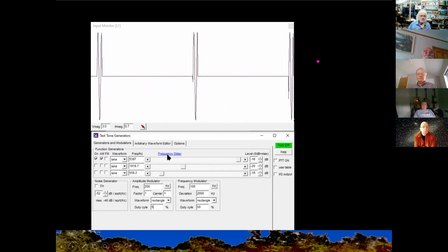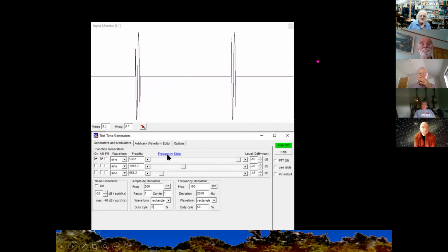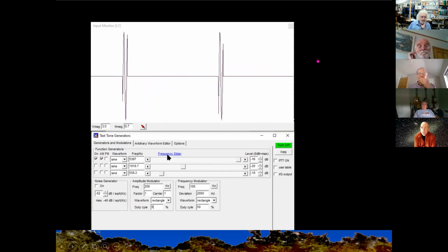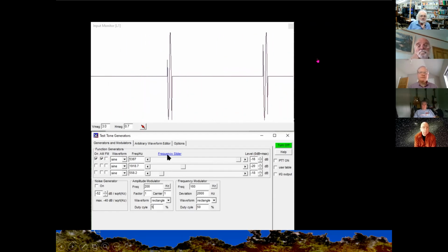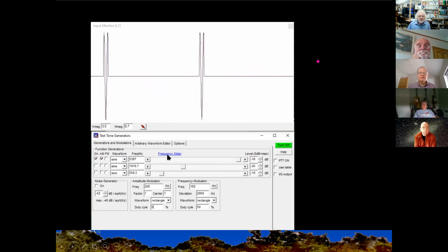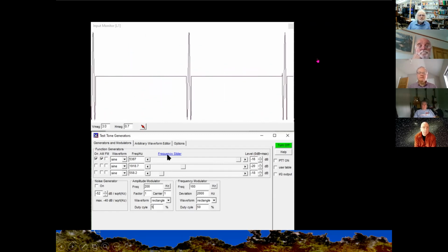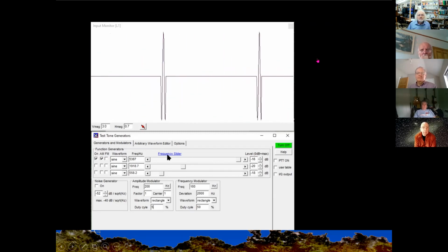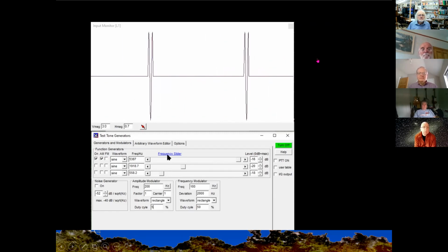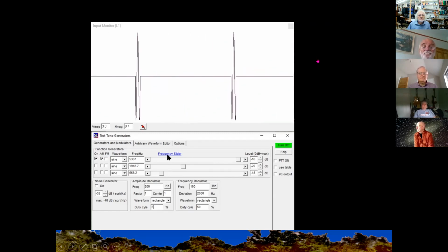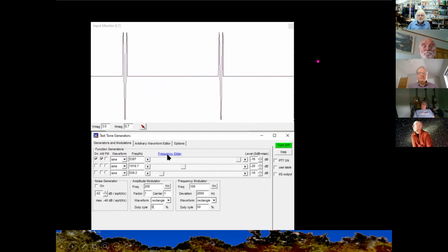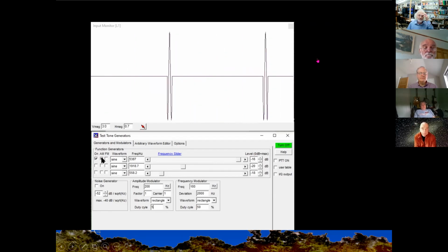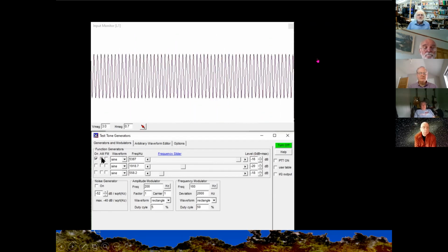And these can be quite useful if you're testing the meteor scatter event detector, for instance. You would think if you're putting equal bursts of equal amplitude signal into the system that you'd get equal measurements out of it, but you don't because of the window function issue. So it's quite useful to actually be able to demonstrate that. But okay, that's amplitude modulation, so we'll take that off.